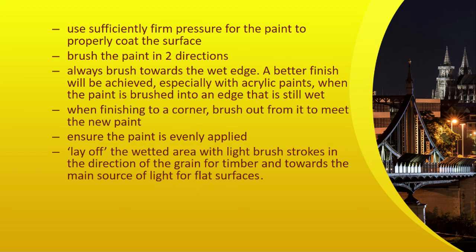Next is brush the paint in two directions. In general, in the direction the light is shining. Next is always brush towards the wet edge. A better finish will be achieved, especially with acrylic paints, when the paint is brushed into an edge that is still wet. When finishing to a corner, brush out from it to meet the new paint.